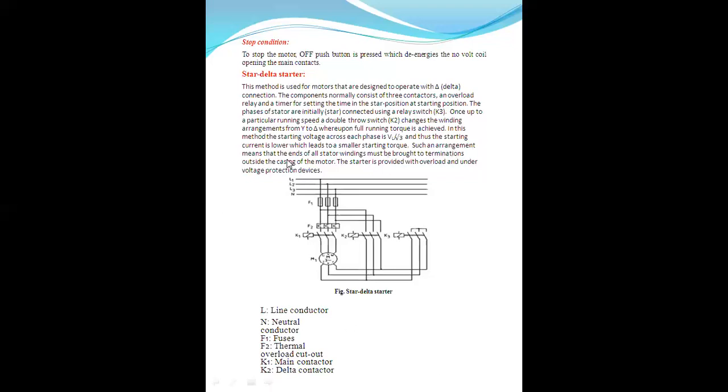Such an arrangement means that the ends of the stator winding must be brought to termination outside the casing of the motor. The starter is provided with overload and under voltage protection devices.